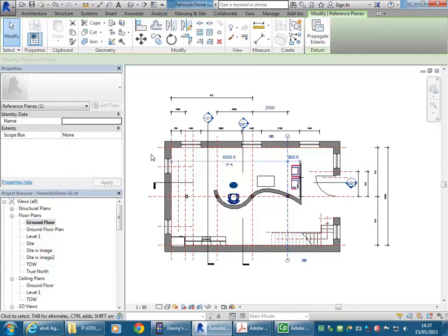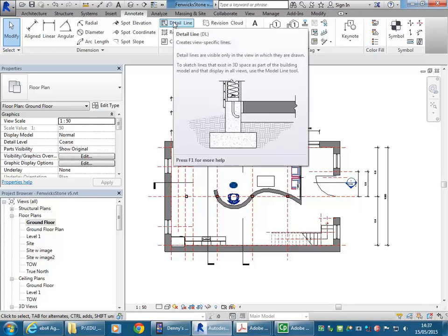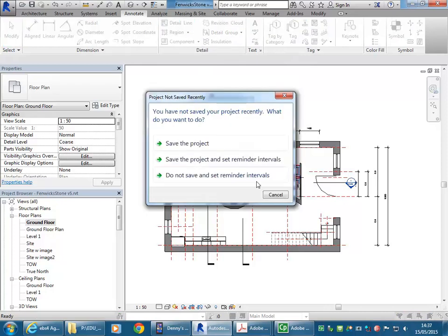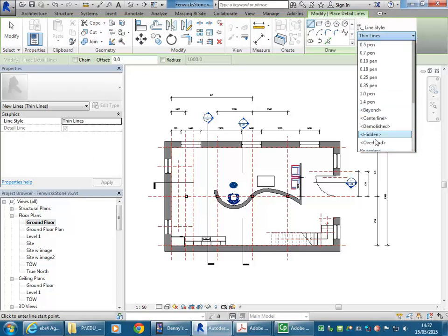With Revit, you'd be surprised how many people, even ones who use it all the time, don't realise that it has these 2D drawing tools that really give you the ability to draw anything you can do in Revit, or really anything you can do by hand. If you're doing line drawing, you're essentially drawing in 2D, and you can set any line style you like. And I don't care what anyone says, a computer is always going to do a better job drawing a straight line than a person is. Accurate, exactly.